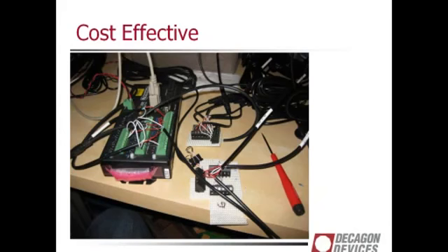This particular logger has 10 SDI-12 sensors, or 9 SDI-12 sensors running on it. 6 sensors here going into COM2, 3 sensors here going into COM1. So you can effectively exponentially increase the number of sensors you can put on one data logger.